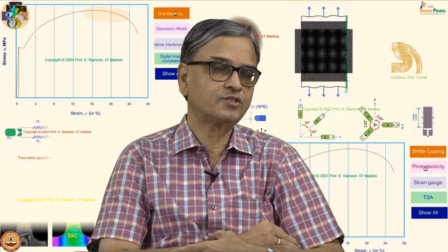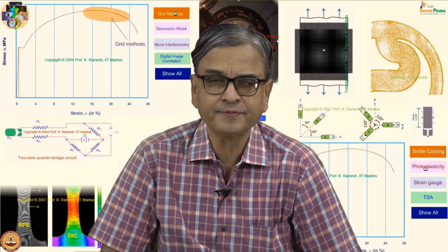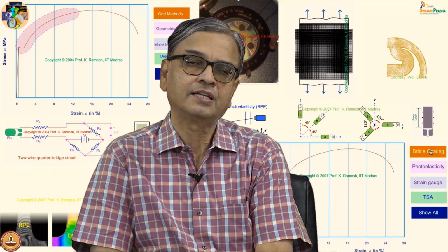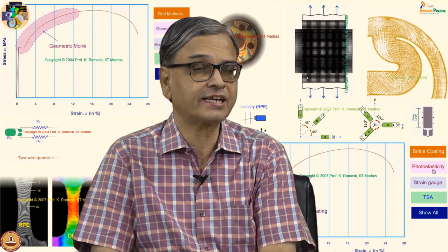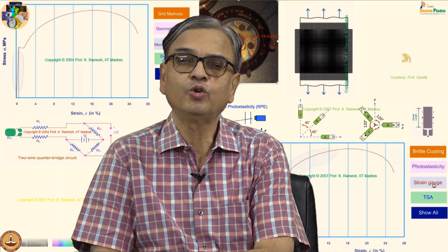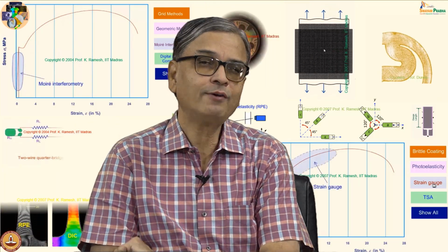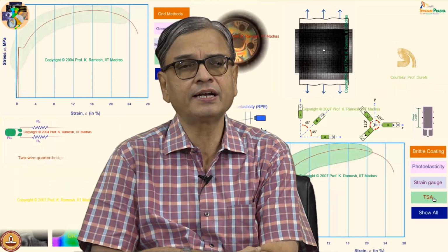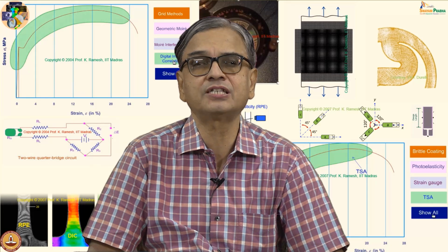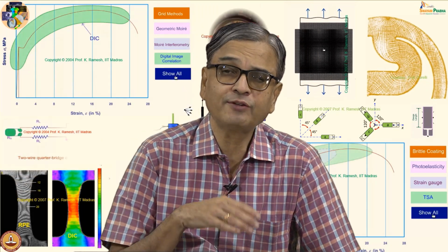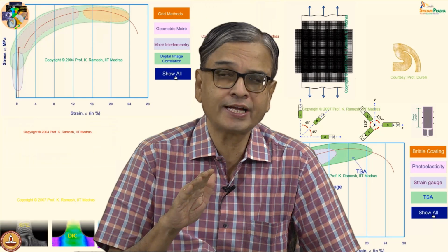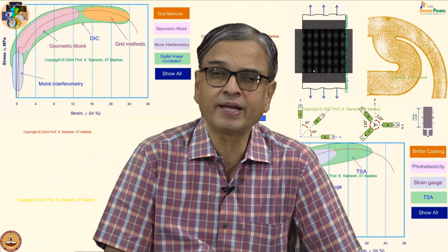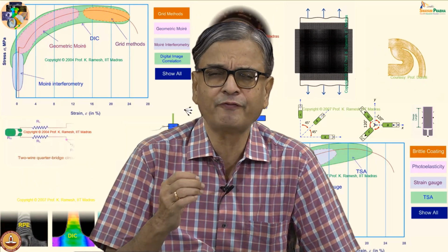See, in the last class we have learnt what is strain at a point. When you say strain at a point, you recognize that you have to refer to state of strain at a point. And when you look at it in two dimensions, you have three components. Fine. And we have also looked at, when we talk about infinitesimal strain, the quantity was very, very small. We are talking about it in terms of microstrain, and we said it is 10 power minus 6 millimeter per millimeter. It's a very small quantity.